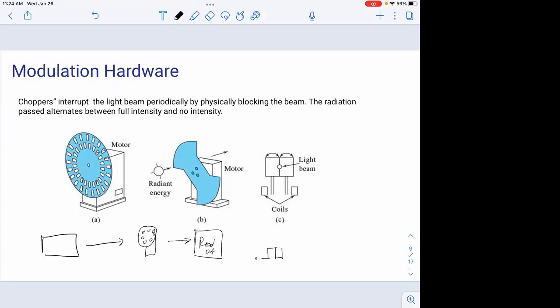So you're going to modulate, and it should be very consistent in terms of the height and width of these square waveforms. And the benefit here is that we are putting the analytical data, which of course is the magnitude of these square waveforms, into a higher frequency range than it originally was. Okay, so then we can get rid of some noise here. So let's talk a little bit about what that looks like.